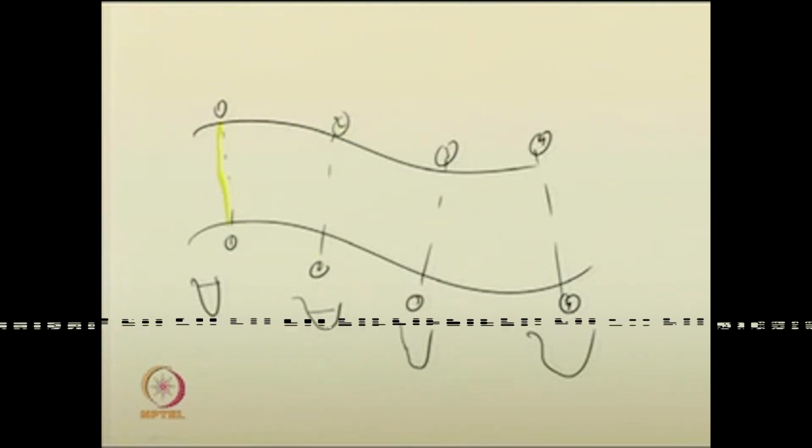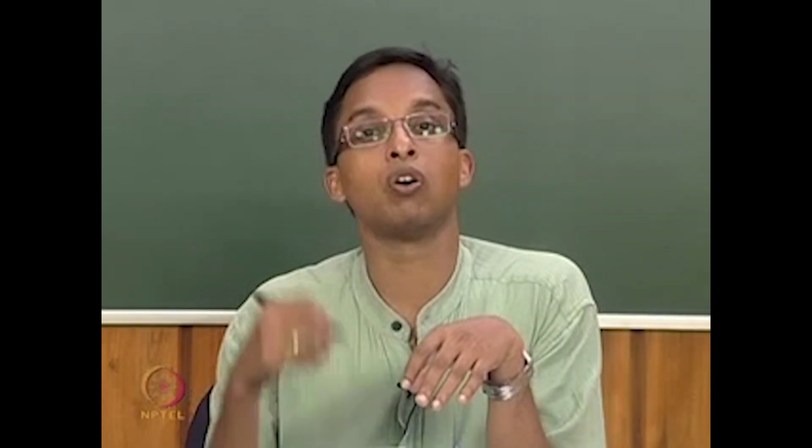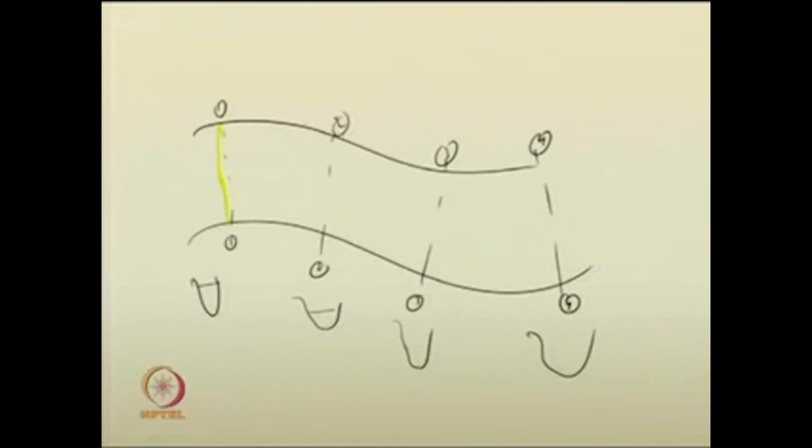At section 2, to evaluate the depth of flow or even the velocity of the flow or even the discharge, as you know, it will be constant, because for gradually varied flow we have suggested that discharge is constant throughout all the sections. So, discharge will be the same, and all these things can be evaluated. You use the known property from the left hand side and you evaluate the right hand side.